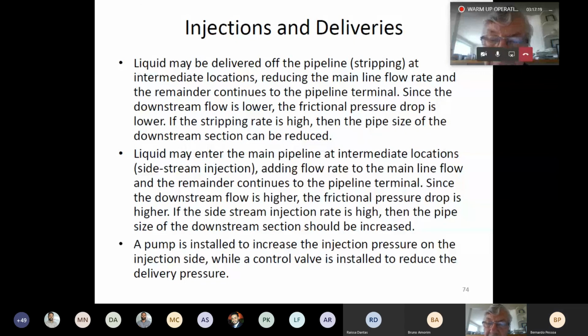Now, you should ask Mike Yoon to give you a little chat about how automatic control works, and I'm sure he'd be delighted to do that. But supervisory control and data acquisition, you acquire the data from remote terminal units along the length of the pipe or at pump stations, compressor stations. And when you get that, then these fellows in the control center, they exercise supervisory control. It's also possible for you to have what are called programmable logic controllers at the pump station. We have local control, but we'll get Mike to tell you about that.